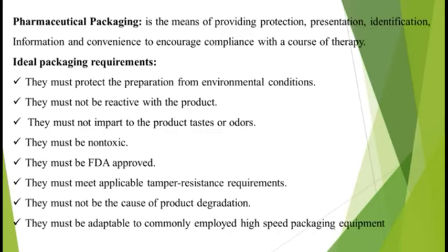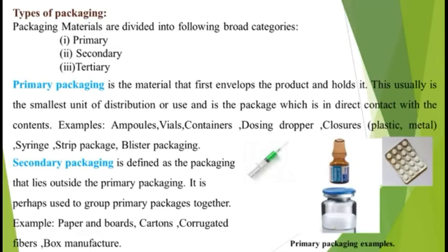And this polystyrene has a low melting point, that means 190 degrees Fahrenheit, and it cannot be used for hot items. So next is nylon. This nylon contains dibasic acid plus diamine. For example, nylon 6:10 means 6 carbon atoms in the diamine and 10 in the acid. Nylon 6 and 6:10.